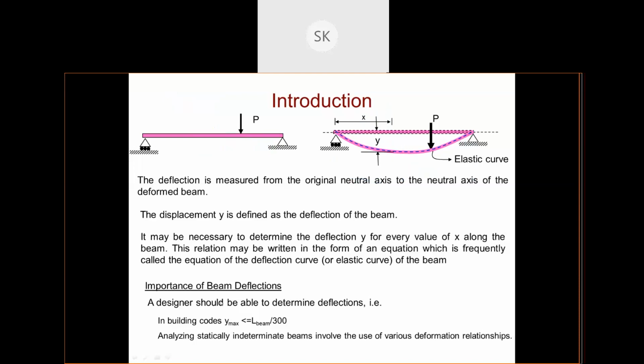And as per IS 456, maybe Junaid sir has told you about this. In design, you need a code, the Indian Standard Code IS 456. As per IS 456, a designer should be able to determine deflection, that is, Ymax equals L by 300. Your Ymax should not exceed this value. L is the length of the beam.